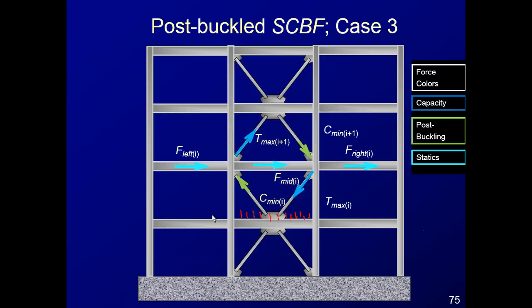Or maybe they might use just a limited length and discount the rest as the collector. And I really don't see anything in ASCE 7 or elsewhere that tells you you can't do that, but you do need to make sure that you have a load path to engage, to concentrate your shear in the length of the collector that you're considering.